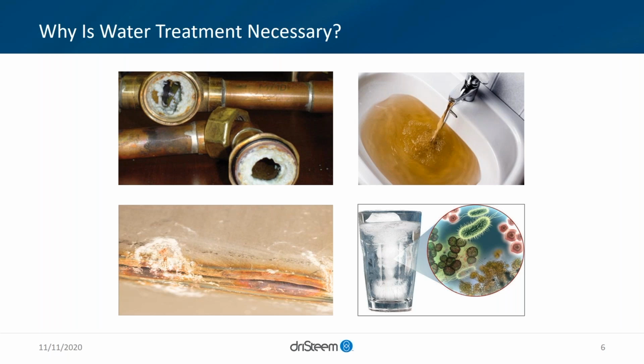In the bottom left, we're depicting corrosion, stress corrosion in particular. If we're not cognizant of, let's say, high chlorides, for example, additional corrosion can occur at the weld, or general corrosion if you have corrosive type conditions.